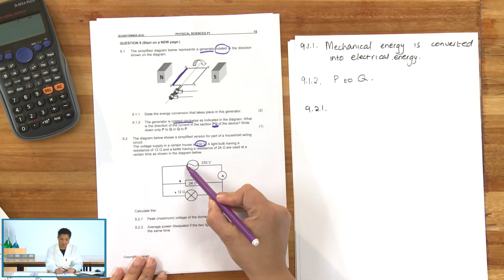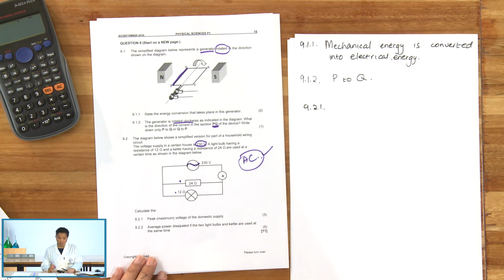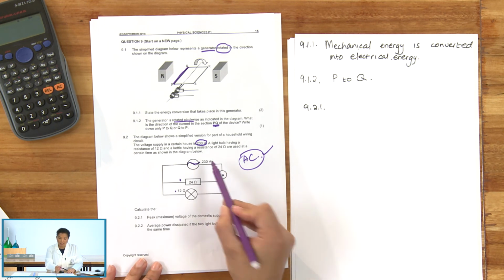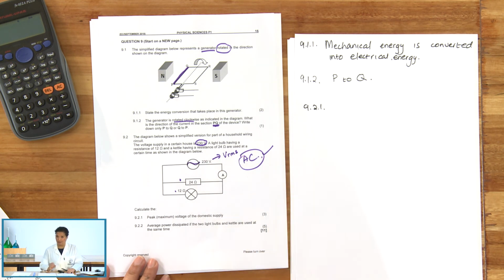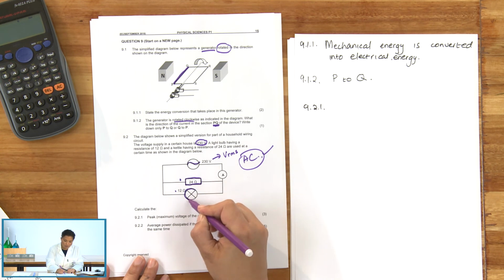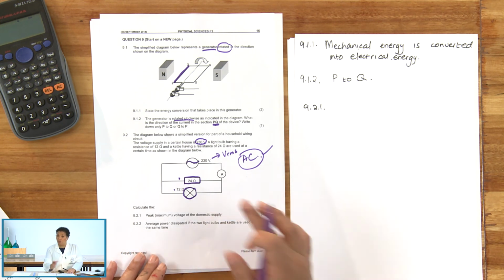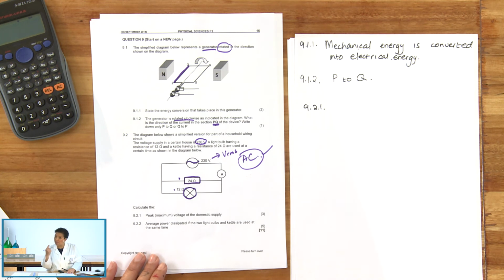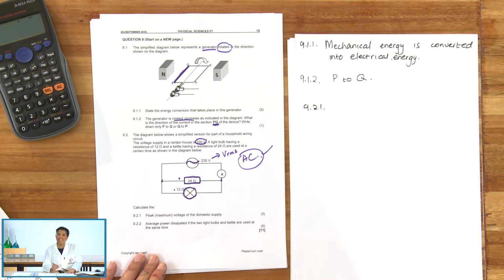Number one, the symbol. I know I have an AC circuit. Check. Second of all, I've got 230 volts. I know that that is my VRMS. Then I've got two resistors. And how are those resistors connected? They are connected in parallel. So I could possibly have to go and find out the total resistance, but remember, if we do, we need to know how these resistors are connected. And there's a branch here, and so we know that these resistors are connected in parallel. So let's go and see.